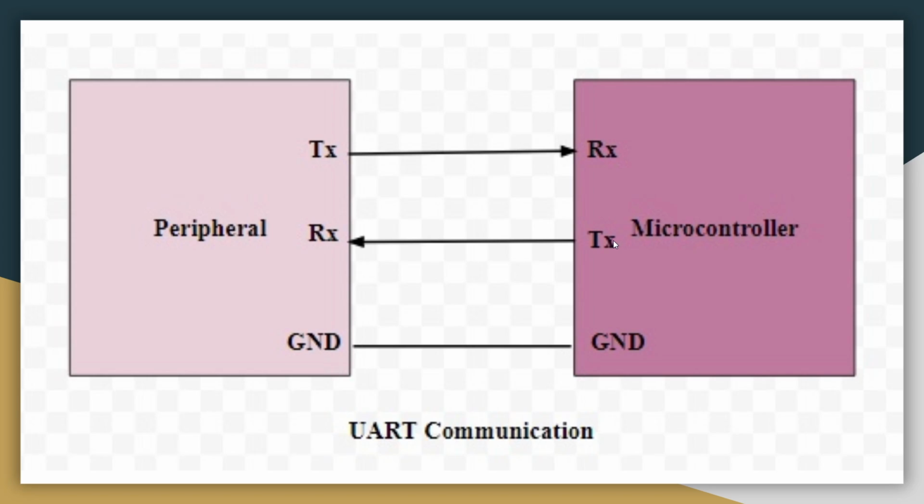The microcontroller doesn't usually write and send anything to the Bluetooth module. But suppose there was some other peripheral, or consider two Arduinos interacting with each other using UART. Then one Arduino's receiver is going to keep receiving the things transmitted from the other Arduino, and this Arduino is going to keep receiving from that one. So it's basically transferring of data from TX to RX continuously.